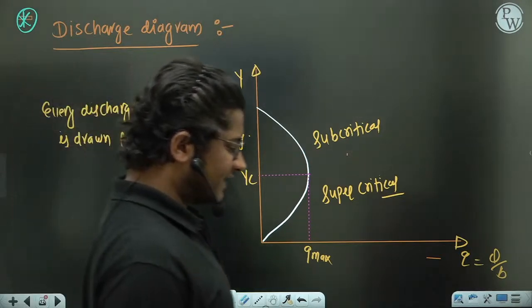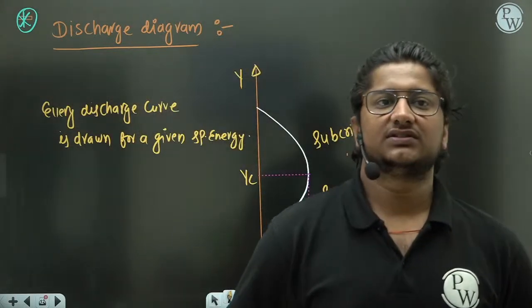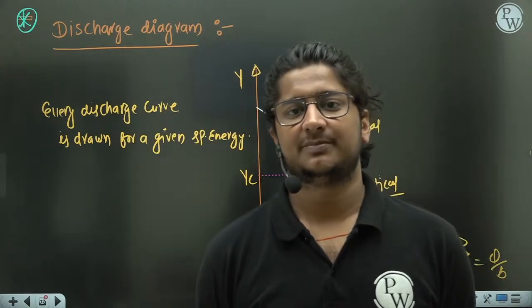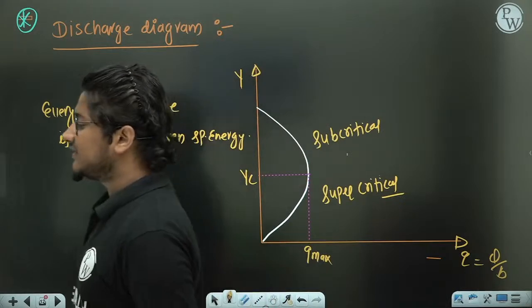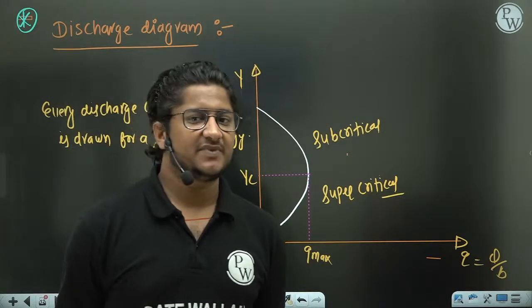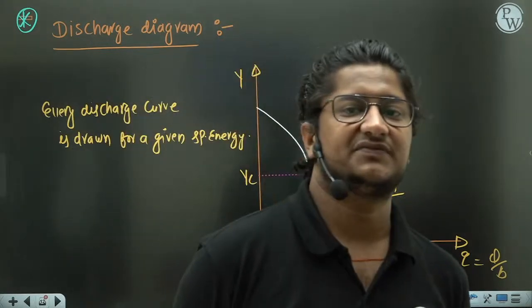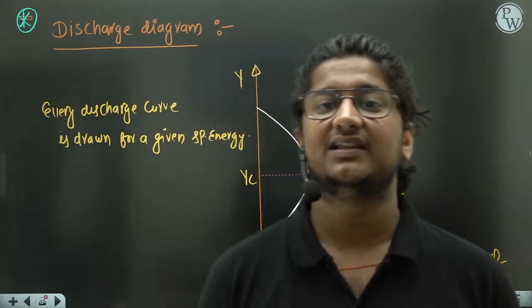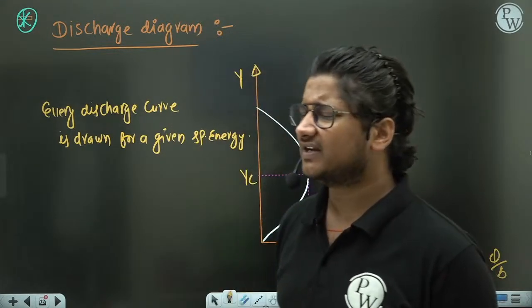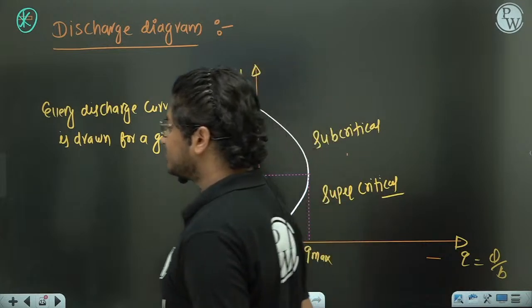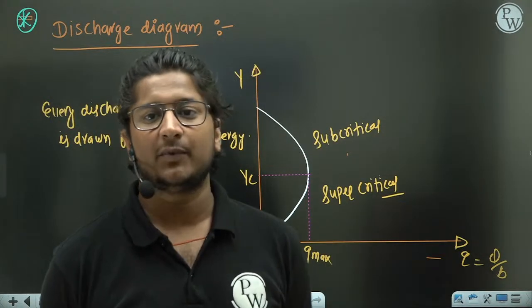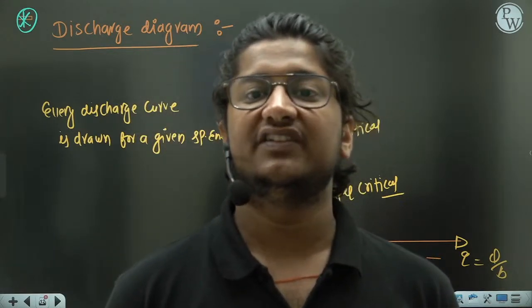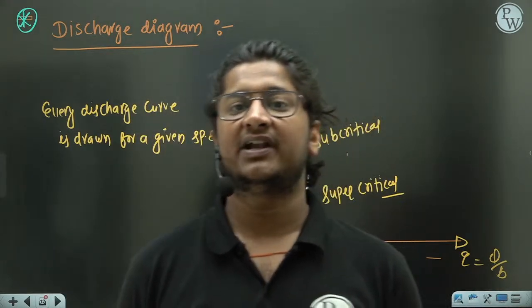Now what happens, my dear? In phenomena like hydraulic jump, where losses are very high, the energy principle, that means the Bernoulli principle, that specific energy principle, will not be able to handle these large losses. You can handle small losses with the energy principle, but for large losses, like in fluid mechanics, to deal with the impact of jet and all, we use the momentum equation.